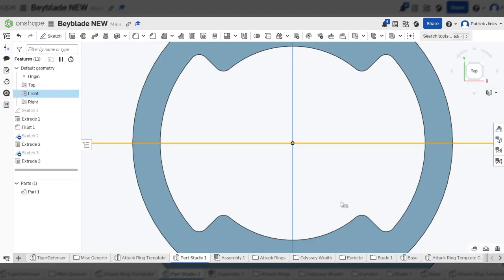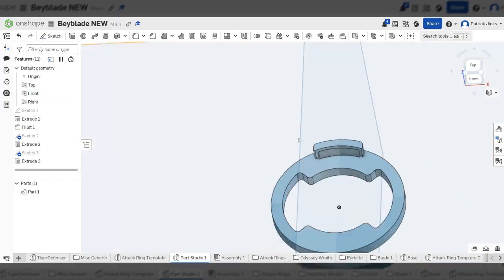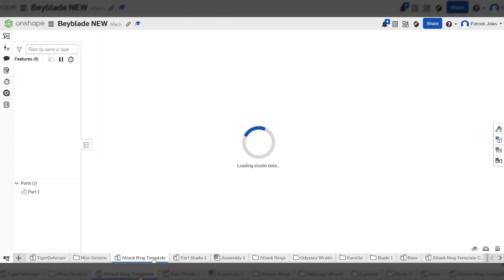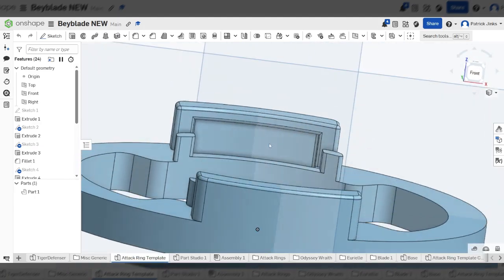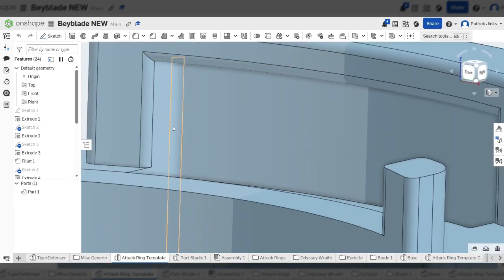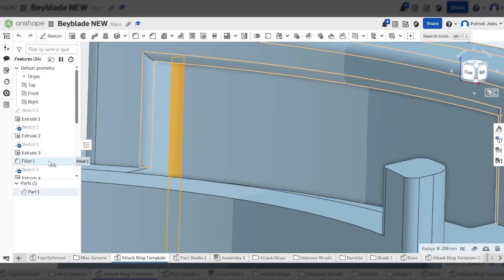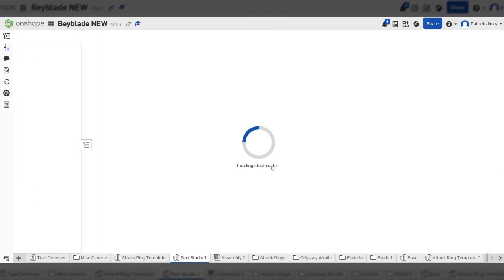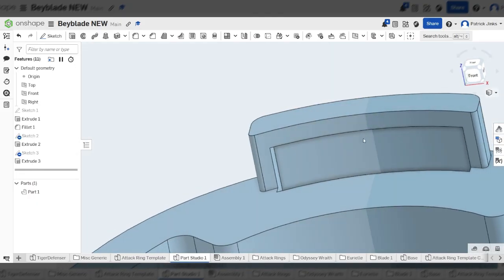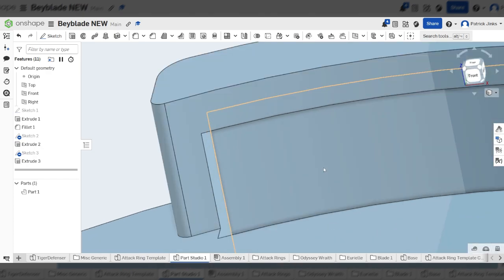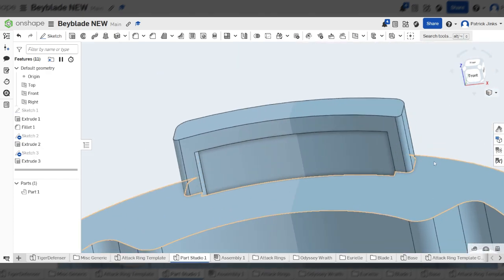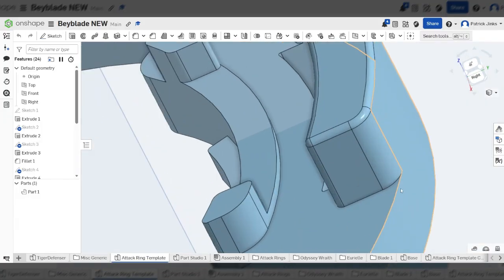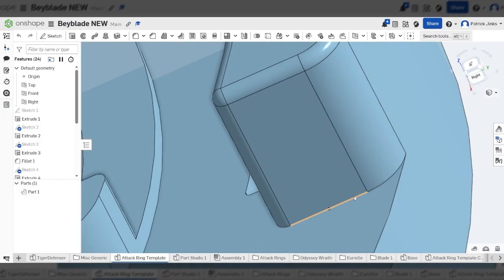Okay, let's just compare this to our template, which had some fillets on, and I can't actually remember how big those fillets were, so we're going to check. That looks pretty good to me. These fillets, they were 0.25. Okay, so what you're going to do is put fillets around the outside of this. What you're going to avoid is putting fillets around this bottom edge, okay?